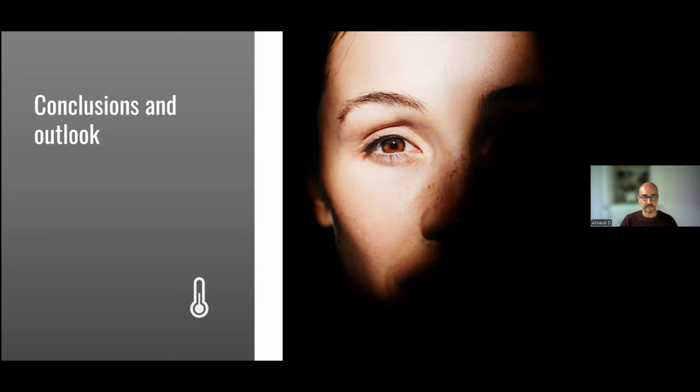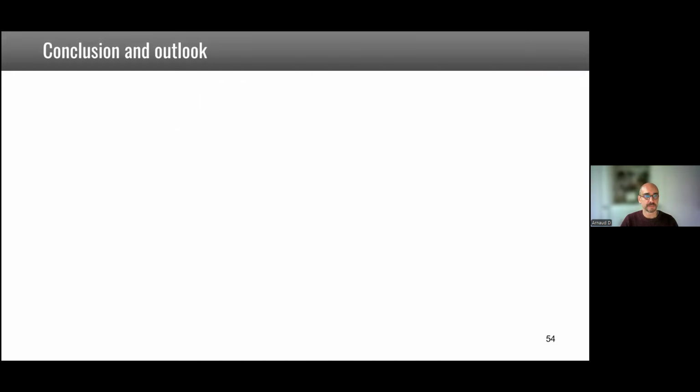Okay, so what are my conclusions of this part? I showed you that in the tunnel example, I first tried to apply a core driver, which is a time stretching. This time stretching was based on the hypothesis that the wave velocity change is uniform in the medium, and obviously it's not. That's why we introduced some averaging moving reference, which improved the situation, but was still not completely perfect.